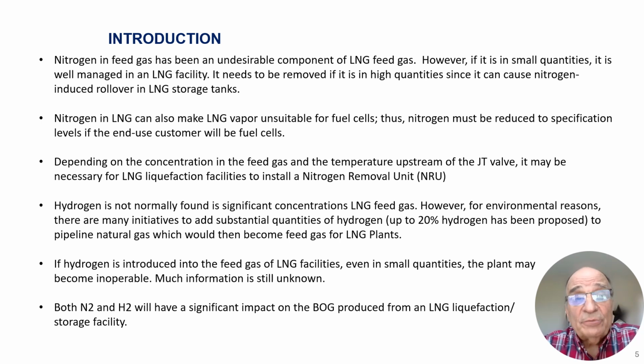Nitrogen can also be detrimental to fuel cells. So if you make LNG and the LNG has a small amount of nitrogen in it, that LNG gets vaporized and sent out to fuel cell customers, it can have a negative impact on the fuel cells. Depending upon the concentration of nitrogen in feed gas, it can also reduce the temperature of your stored LNG. What we have to be careful of is that our tanks, for the most part, and I'm talking about large atmospheric tanks, are rated at minus 260 degrees Fahrenheit. If you get colder than minus 260 degrees Fahrenheit, we'd be operating outside of the design range of those tanks.